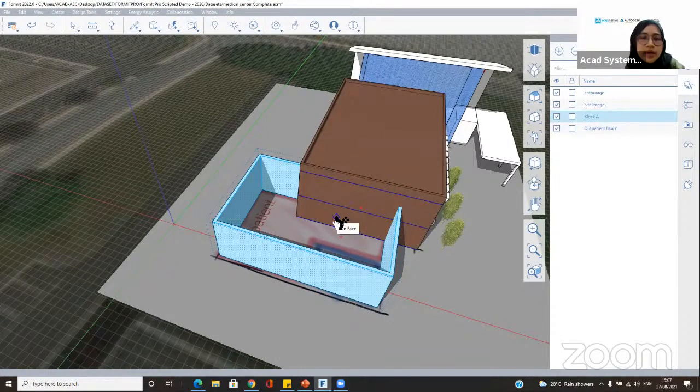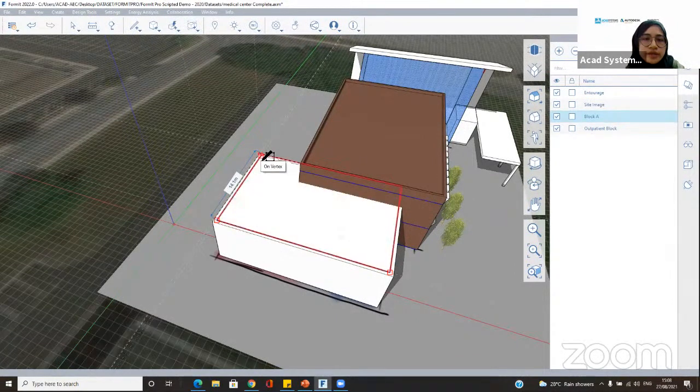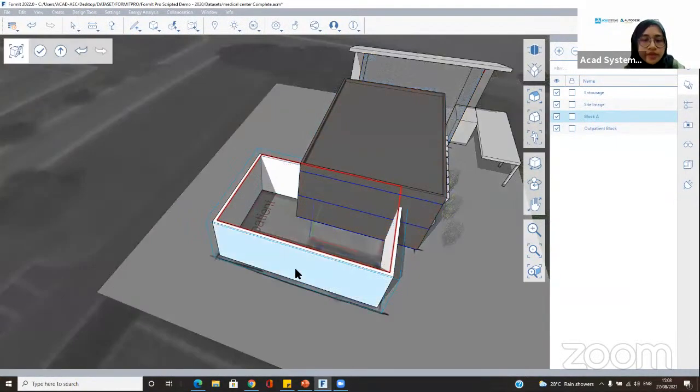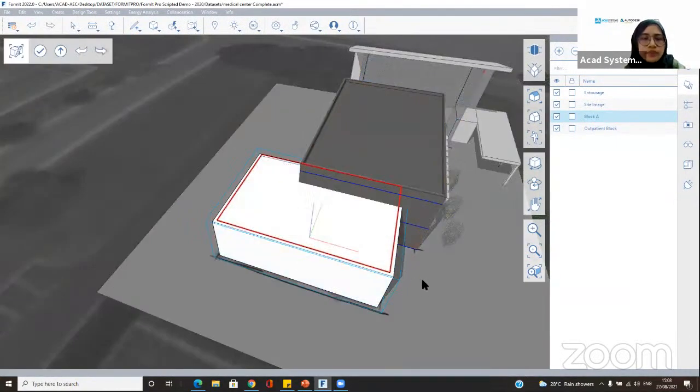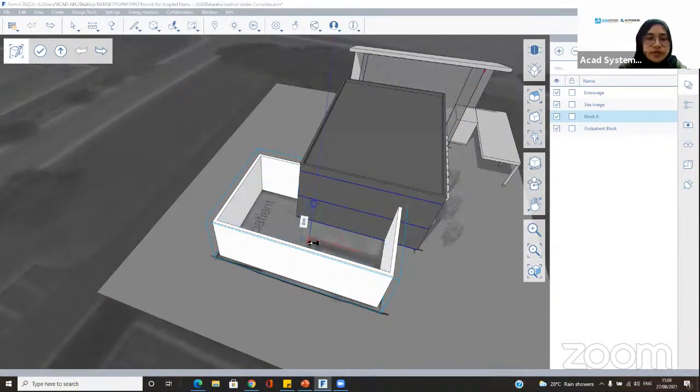It intersects with that. But before that, let me just add another one here, the roof profile. So I'm just going to go again to rectangle. This is where we can access all the sketch tools. Rectangle, and select this point. Oh, this is not good. We select this point, and this point. Then right there we have it. Oh, we just go again to have it inside the group. All right, so I'm going to do this one by 7 just now, and I can have the new rectangle here.